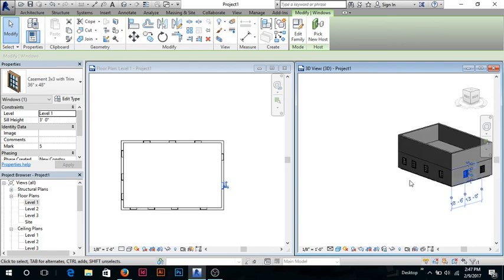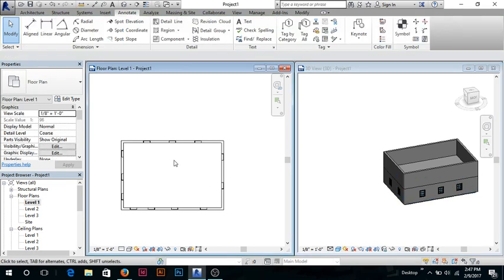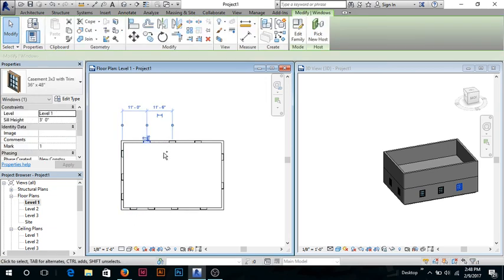I like the placement of everything. These are great. Aligns with the living room, the kitchen, and so on. And then your boss says, okay, but I want the upstairs windows, or your design, you want the upper level to be exactly the same. A small trick, you can click each wall. If you hold the control button, you get this little plus sign on your pointer, basically. And if you hold it, you can just highlight all the windows, which is great.